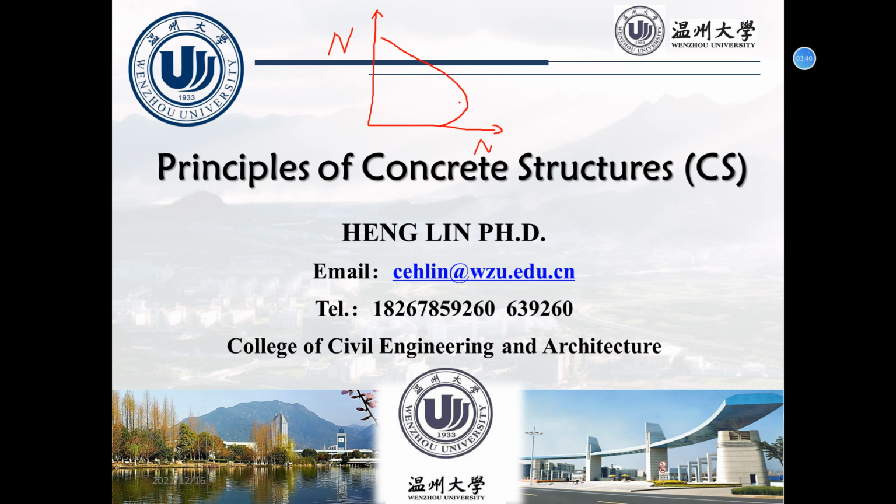For the curve, we introduced 3 failure modes. The first is the balanced failure mode. For columns, it is only 1 point. A balanced failure is when the concrete and the steel bar reach yield at the same time. The higher part is the compression failure mode, and the lower part is the tension failure mode.